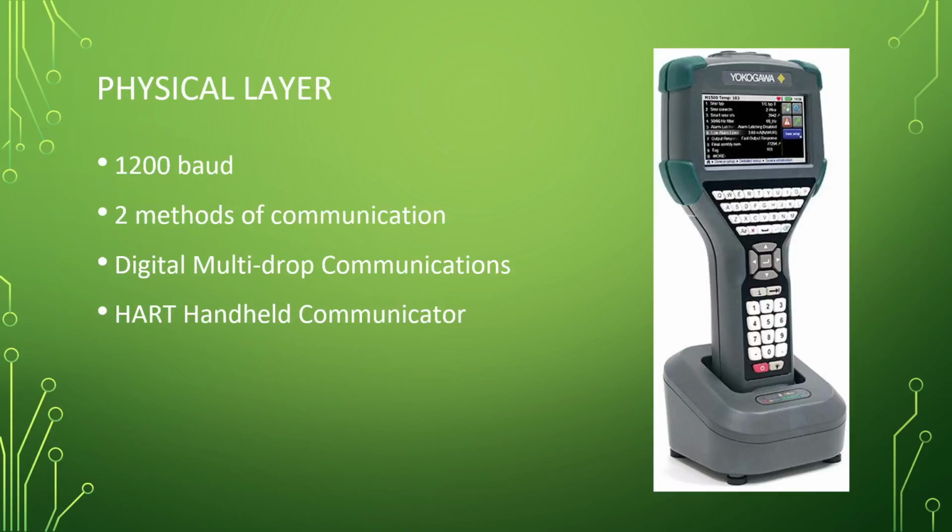All right. Next comes the physical layer. We have our little controller here. This is what you would actually plug into that network to decode the information that's being sent. Could you do this on the PLC? Yes, but this is a nice little handheld device that you could add in and the PLC would still be able to function. As the video talked about, we do have a multi-master environment, so you could actually have like 4 of these things plugged in and they will work.